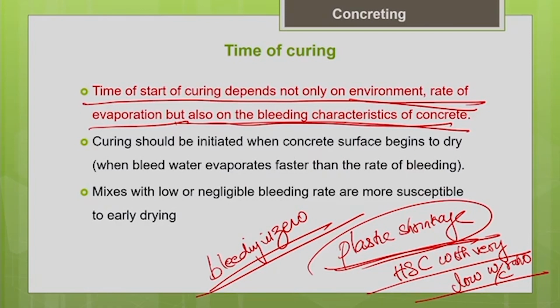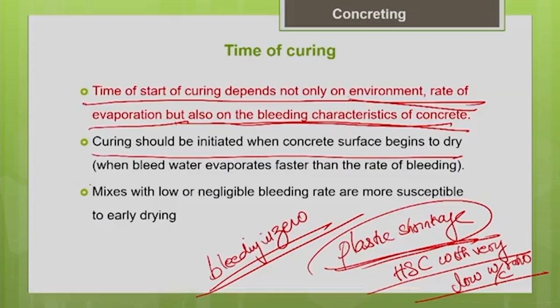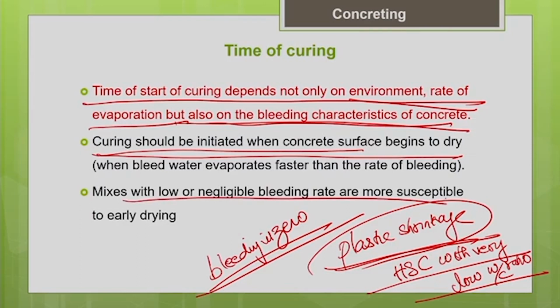Curing should be initiated when the concrete surface begins to dry. So, when the rate of evaporation is faster than the rate of bleeding, obviously it indicates that the curing should be initiated. Mixes with low or negligible bleeding rate are more susceptible to early drying. That is what I told you.